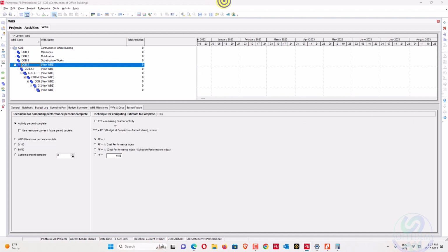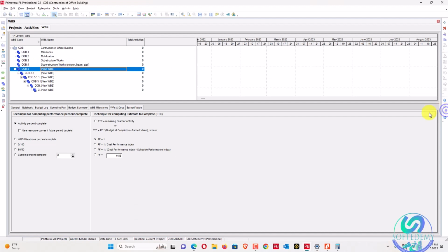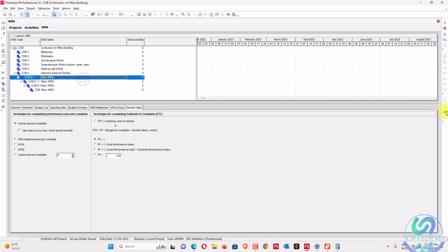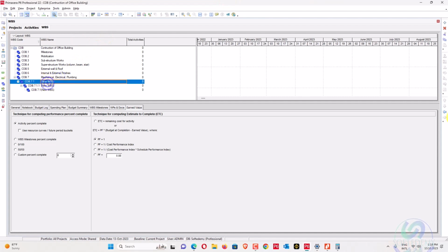Copy all down. There is also an option to add them from an array. You cannot import WBSs that way, but there are options. You can also add the activity code instead of this one. Activity codes can also be added because it's not written that you have to assign WBS necessarily. But I will go for the basics because most practices are based on WBS. Only CBS, cost breakdown structure, is based on your activity codes. So I will consider the cost basis only for the CBS with the activity codes.